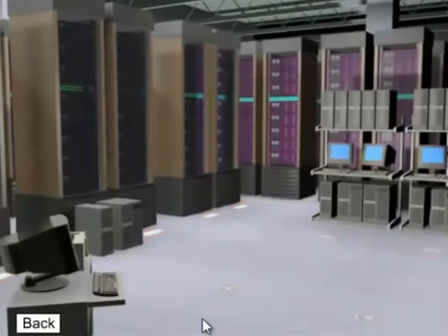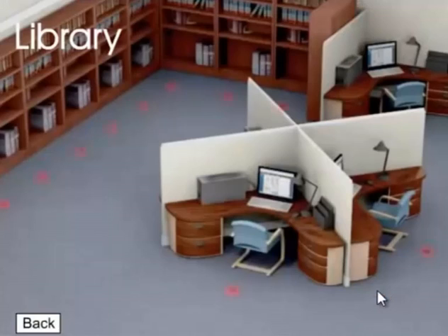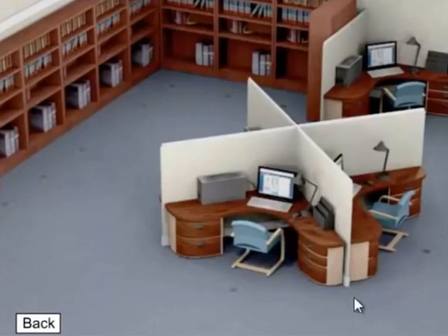Server room. In places like this server room, underfloor diffusers lift the heat and contaminants up and away from the equipment and into high-level returns near the ceilings. Library. The extremely quiet underfloor diffuser is an efficient supply system for places with high ceilings such as libraries.